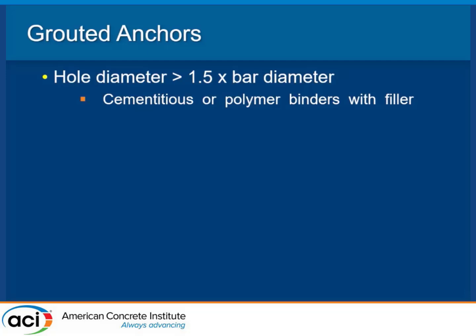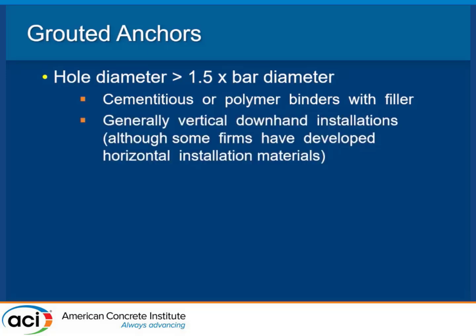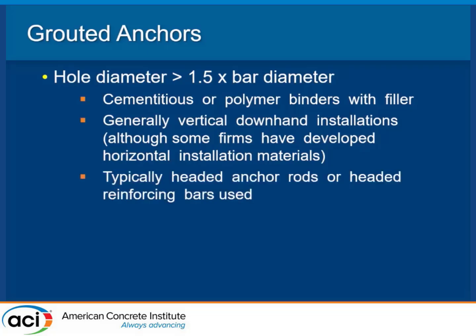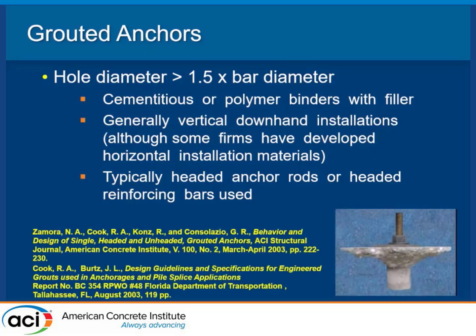However, they have been used very successfully over the years. So it's just something, I guess, we haven't quite been able to pin down as well as the other types of anchors. So when people do use them, they generally use them in vertical down installations. Usually they use a headed rod or headed reinforcing bars.